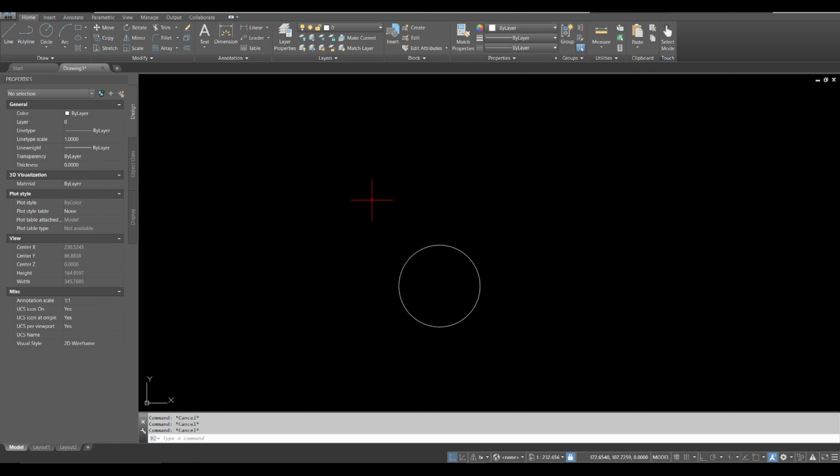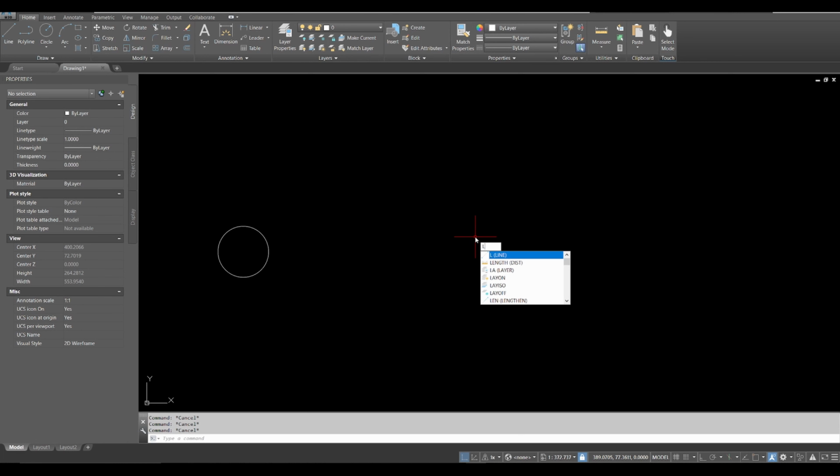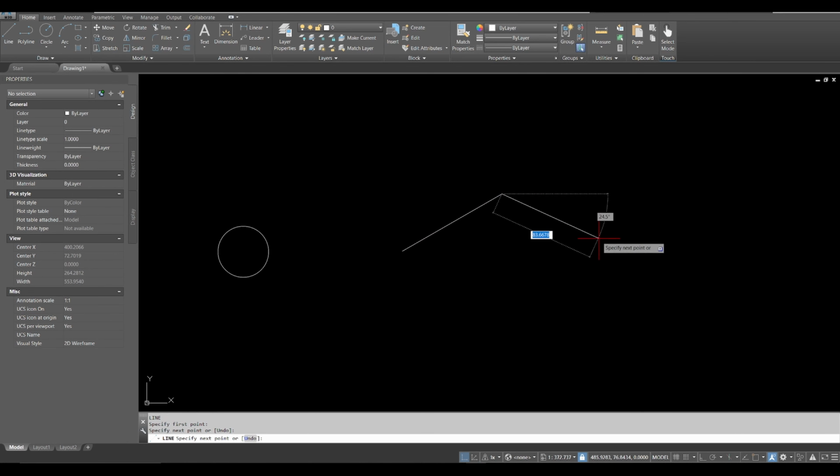So moving on from that, as I was saying with the line and polyline commands, at first glance they seem really similar, right? And for our purposes here, they do differ dramatically, but the main distinction between line and polyline is that when I draw a line using L space, and I specify all these different points, I hit escape to exit my command.